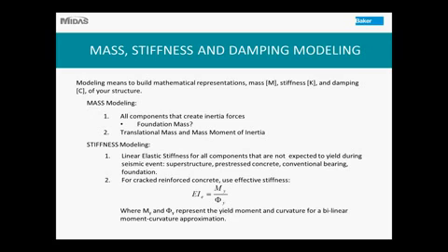The answer to that question, per criteria 1 here, is that every component that creates inertial forces needs to be modeled. If you have a rigid foundation type, your foundation mass is like a rigid attachment to the ground, so there will be no relative displacement between the foundation mass and the ground. So there will be no inertial force generated from the foundation mass, and you do not need to model those foundation masses. However, if you have a foundation flexibility,